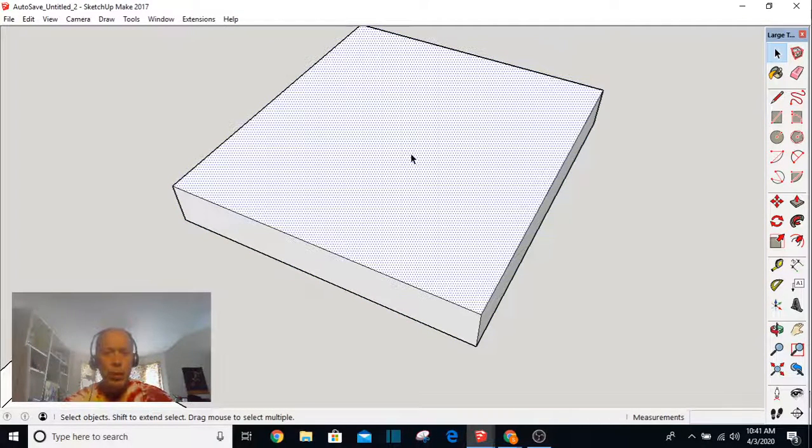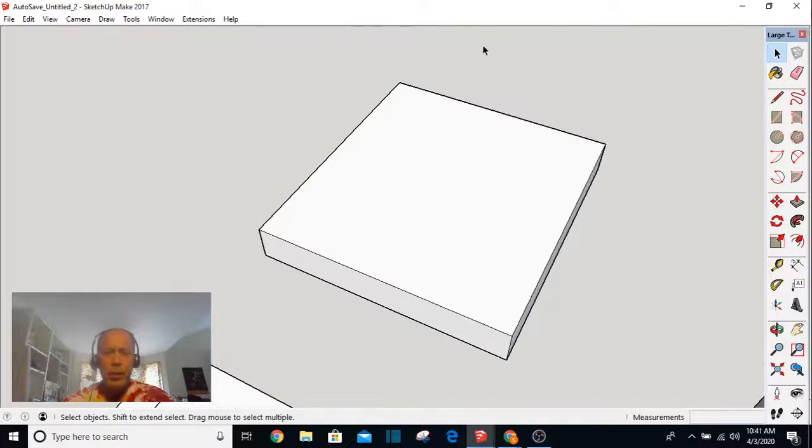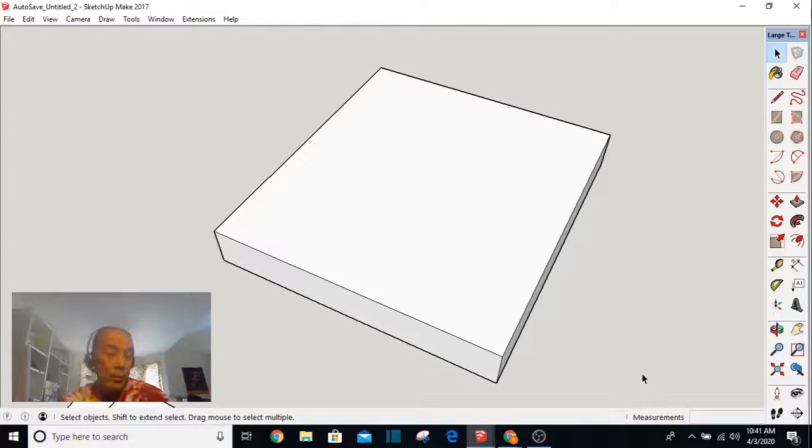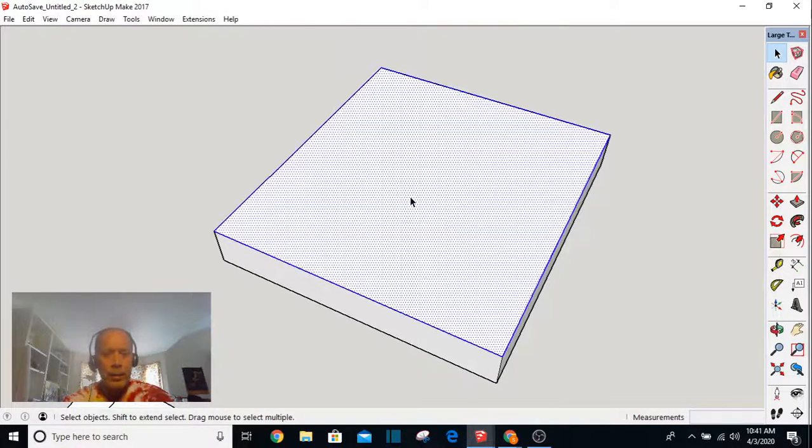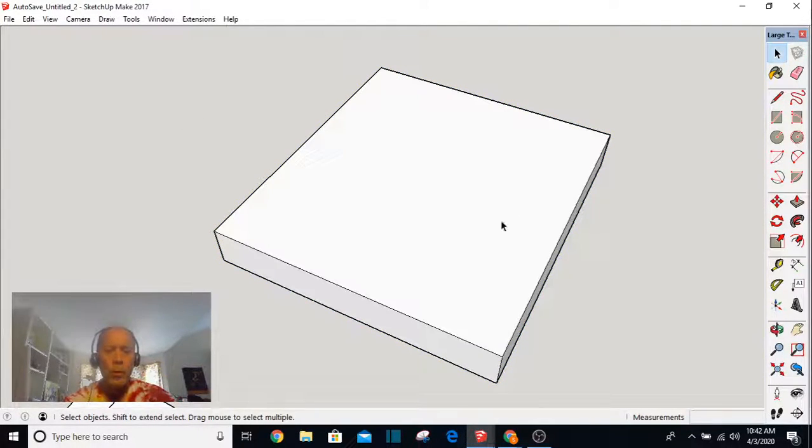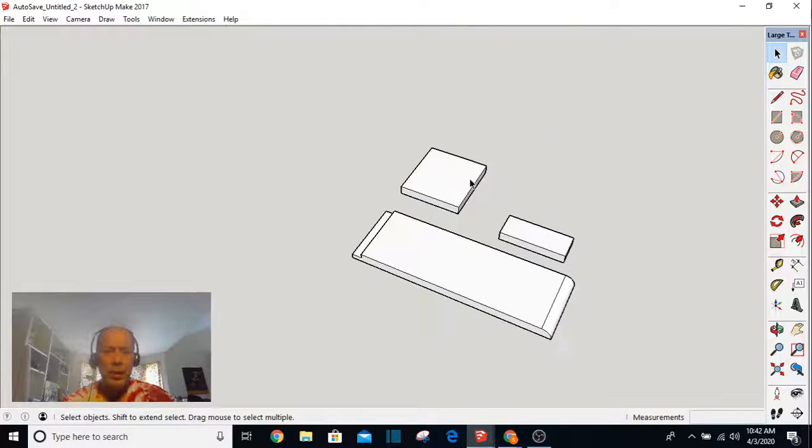So now when I select once, I select the surface. Select twice, click, click, and I select the surface and all edges. Click, click, click, I select the entire object. I suspect that people who are having difficulty selecting their object entirely are doing a click, click, click, which doesn't work. But click, click, click works. So you need to do this in a syncopation that you'll get used to once you've worked on this program more often. But there are other ways to select things, and let's talk about that.